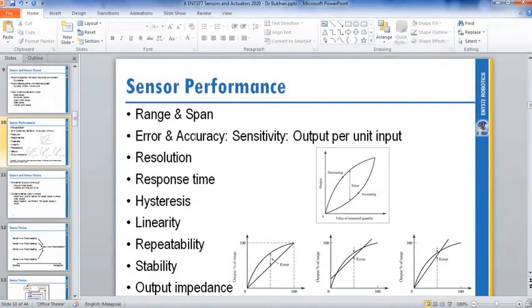But if you turn it on continuously, your sensor gives 10 degrees. You leave it on for 1 hour, and your sensor gives 10 degrees. That one is accurate. But if you switch it on and off, your reading is unstable. That one is lower repeatability. If you switch it off and on, and your reading still gives 10 degrees Celsius, that means your sensor has good repeatability.